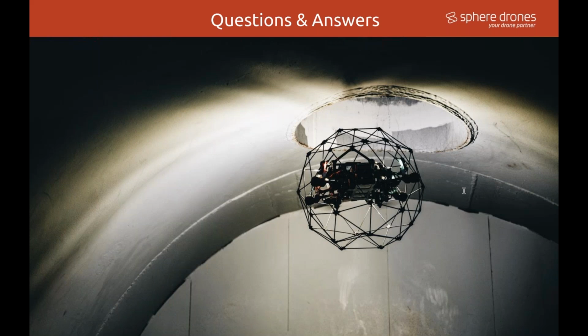Sure. Another question that's come through is, how do you deal with homogeneous environments when creating the 3D models? If you're operating in an area where maybe there are some shiny metals, what are the results like there? Well, shiny metals just don't work, because the software can't get any reliable fixes on the points that it's seeing.